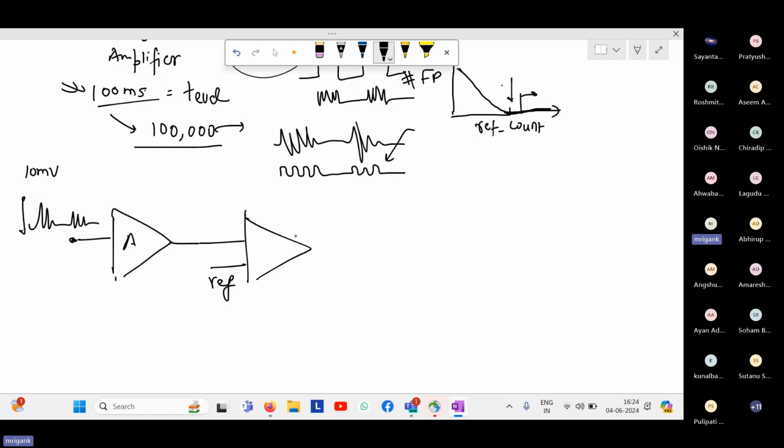So if somebody tells you that we have the target electrode that will be sitting on the scalp, so this is the scalp, that means your skull, and you're going to put the signal over here. Some people have also designed implantable ones, where the sensor goes inside. So suppose it is outside, and this probe is basically giving you the data to the chip. So the chip is sitting here, you have the amplifier here, you have other things, ADC and everything after this. So ultimately I will have to observe what signal magnitude I'm getting here, right? Based on that, I can decide what should be the range of gain.